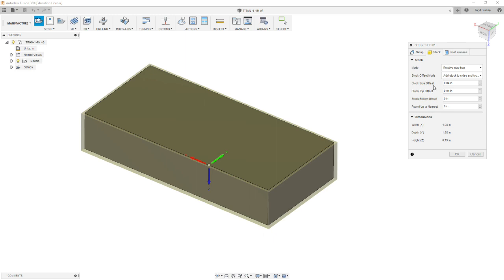Our material is bar stock that is 1 inch by 2 inch by 4 inch. It's cut from a bar. The bar sides will be finished pretty well, and then the two ends of the 4 inch dimension will have saw cuts on them. So our model finished part is 1.9 wide, so we need to add 0.05 to the sides to account for the thickness difference between our finished part and our model part.